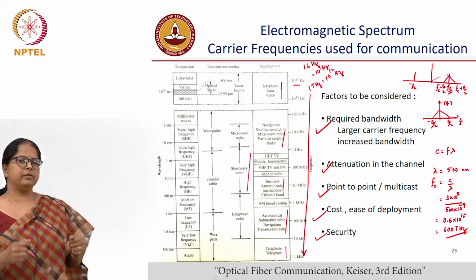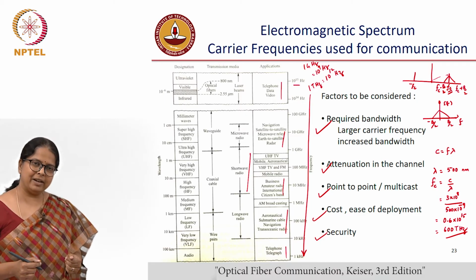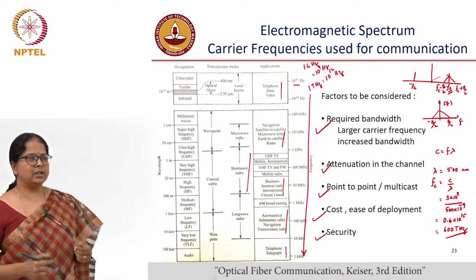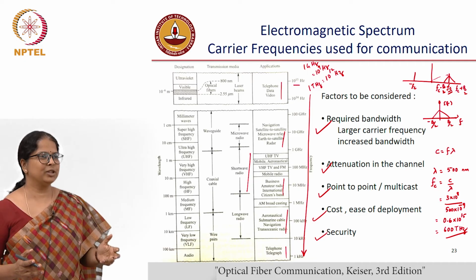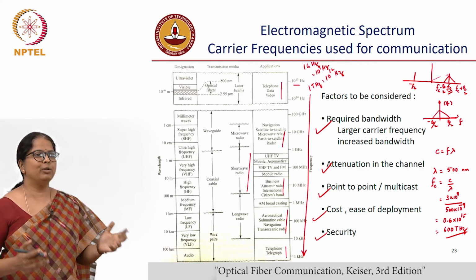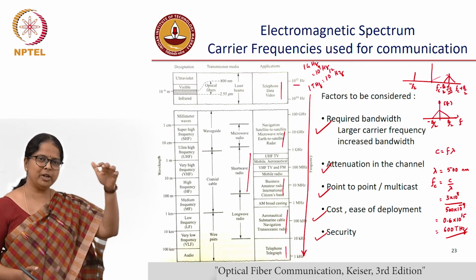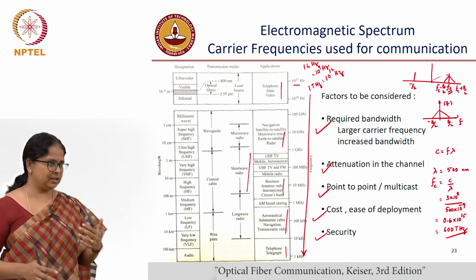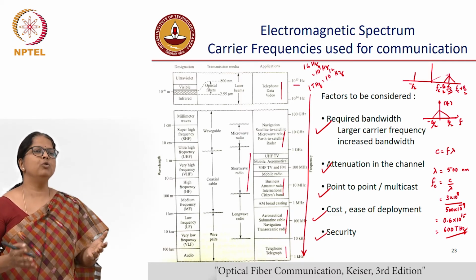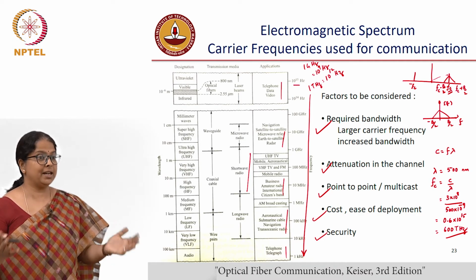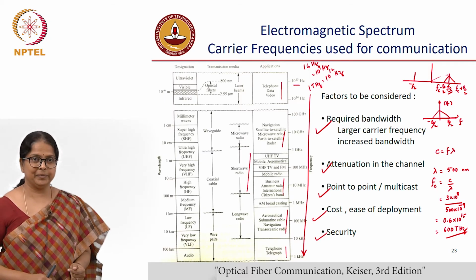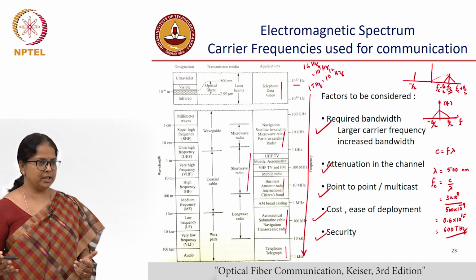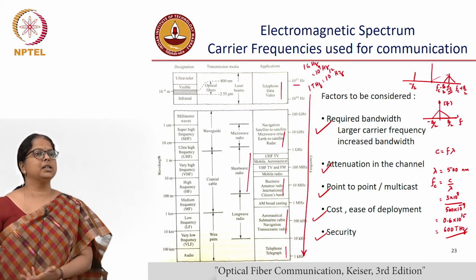Green, by the way, is one of the favorite wavelengths for communication for a specific use case. What is it? Underwater communication. A submarine wants to communicate with a buoy, or between submarines there is a communication link. Green or blue green is a favorite color because channel attenuation is minimum for that color, for those frequencies. So if you are using submarine free space optical communication, you would choose 600 terahertz as your carrier frequency.